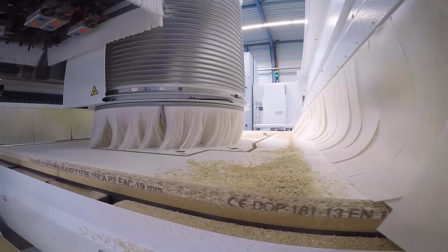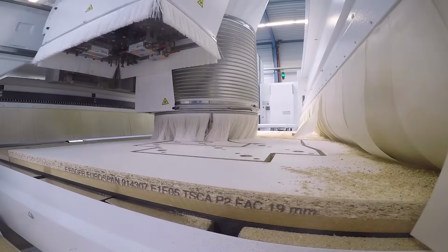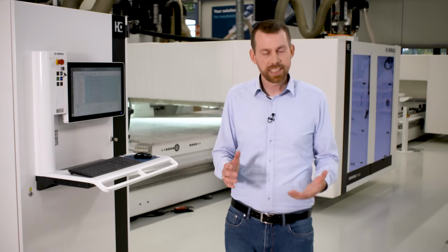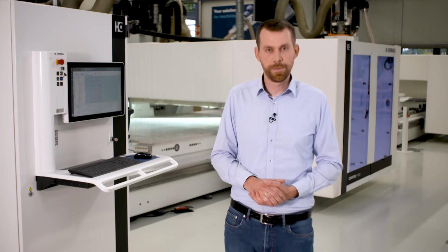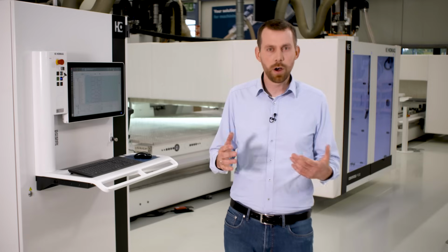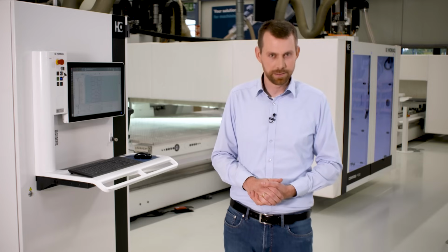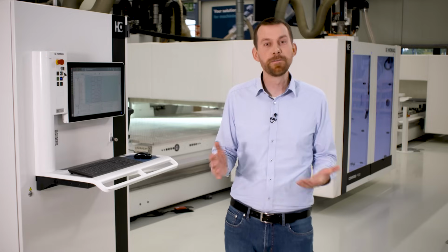With common line nesting, the tool also remains in the material, but at the same time formats the workpieces to the left and right of the cutter. This process is much faster, but the tolerances are greater. You can use the nesting plugin directly in woodWOP. It can also be used in our optimization software, IntelliDivide Nesting. As you can see, there really are a variety of options.